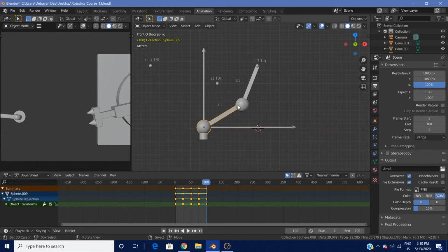search for trajectory planning. And yes, you could use an Arduino with XYZ coordinates if it is for a very small amount. The thing is that, again, if you are using just XYZ coordinates, using your Arduino, you'd say you have to go to theta 1. Arduino has inbuilt functions to go to theta 1 and theta 2 and stuff like that using your servo motors. You could do that, but the actual path followed by the arm will be slightly erratic. It would be something like this. As you can see, the path is not a straight line.